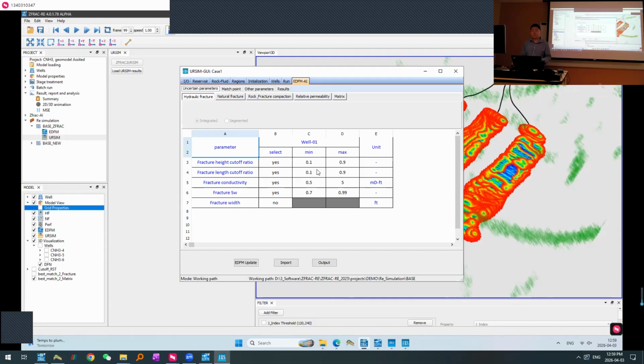One of the most important one is the percentage of the effective fracture geometry compared to your wetted geometry. As we know that if the well is put onto production, some part of fracture closes, and not all fracture lengths or height are effective, are contributing to production. So we can play with different ratios of effective geometries for both length and also the height direction.